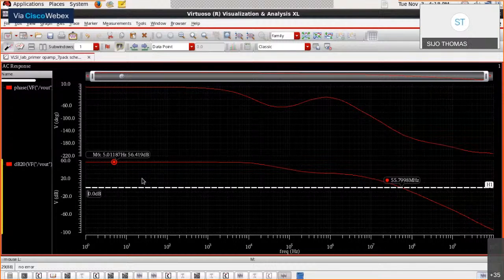But isn't L equal to just 250 nanometers and W equal to 10 or 20 microns something which has a small length and is very wide? Yeah, short channel effects will come into picture there. That is fine, but in analog, I anyway require devices to be large. My choice of L essentially depends on whether I want large bandwidth or large gain. So I need to take a call, and I may want to iterate.